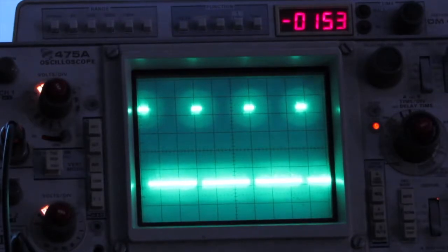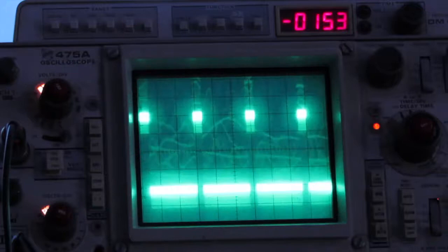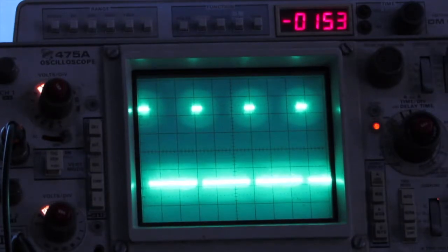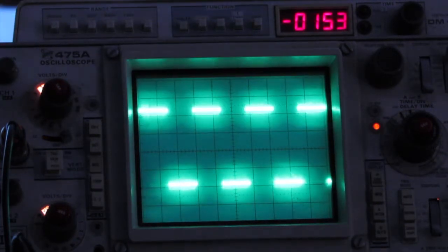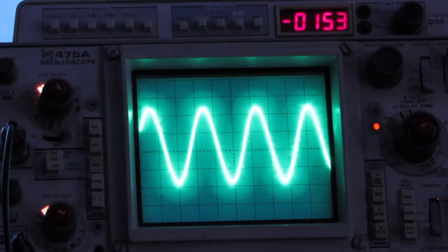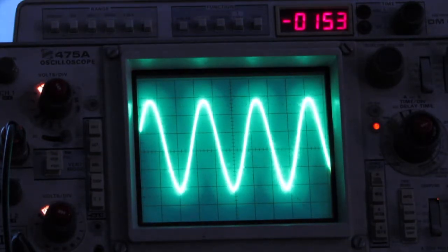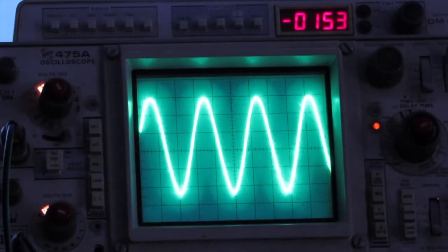I want to move on to a very important part of the oscilloscope called the trigger section. If any of you have fooled around with a scope, you may have been able to get the voltage and get the sweep to work and everything like that, but you can't stabilize the signal or really look at it to measure it. And that is what the trigger section does.